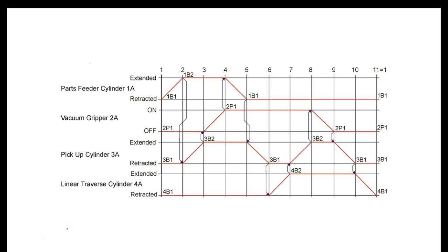When the rotor starts up, the pallet's supposed to move upward. Somebody went there and placed washers on 3 of the sensors over the weekend. Those sensors are not really accessible while the line's running, so we had to try to figure it out. It took us a good 20 or 30 minutes to realize what was going on.